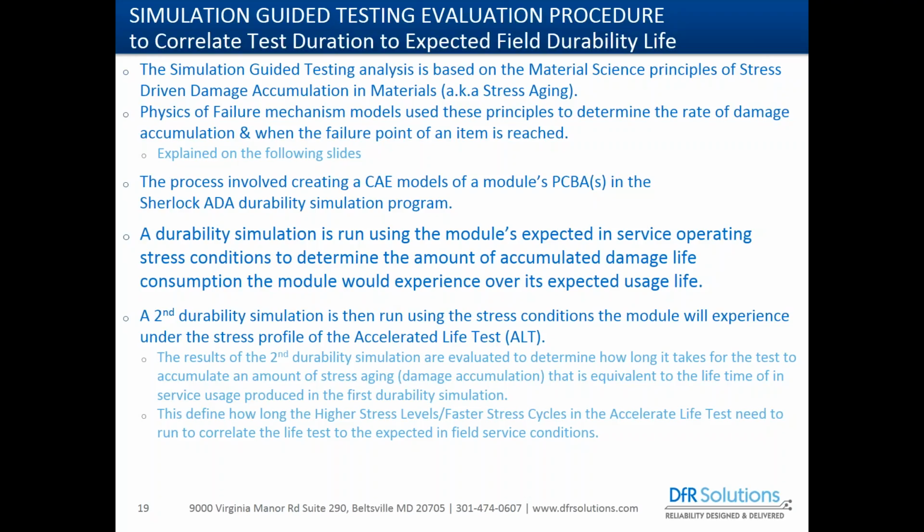A second durability simulation is then run using the stress conditions the model will experience in the stress profile of your accelerated life test. The results of the second durability simulation, using the same device product design model, can then be evaluated to determine how long it takes for the test to accumulate an equivalent amount of stress aging, damage accumulation, to what is built up in the field lifetime usage scenario.